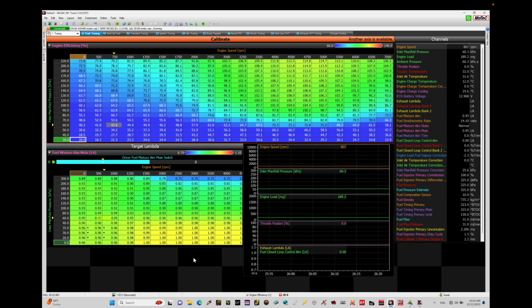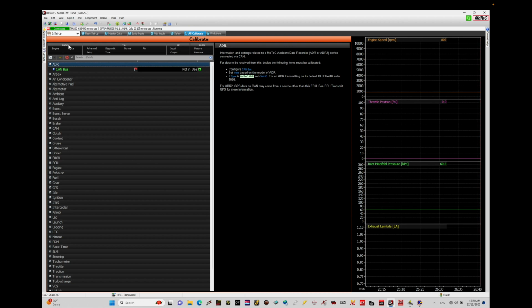We're going to have that in future tutorials, but let's jump in here and take a look at understanding the fundamentals of working with output programming so we know exactly what to expect when we're trying to control a particular circuit. So let's jump in here. I'm going to move from my tuning page in my workbook I provided for the training course and jump down here under setup, and we're going to move here into the all calibrate window.